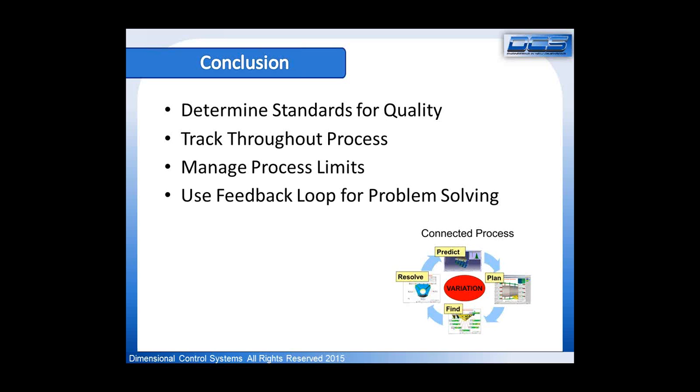repeatable issues. I think that's one of the key aspects of this, that repeatable characteristic, being able to be identified through process capability data and be able to apply back to considerations in the product design, so that you can manage these process limitations and start to get a better understanding of where they exist, what the limitations are, and what you can do to account for those limitations earlier in the development phases, using the feedback loop that we've talked about repeatedly here.